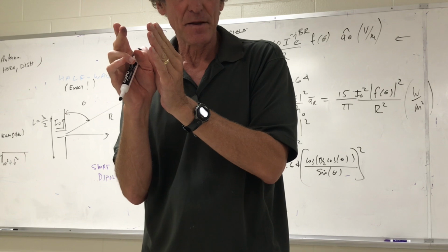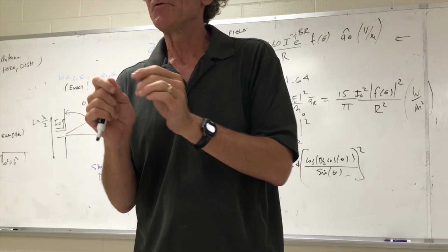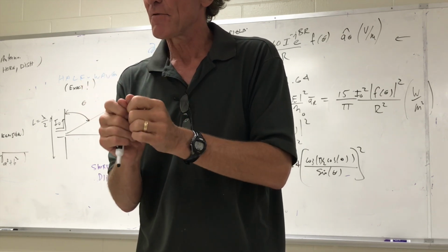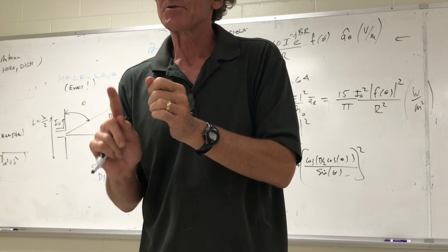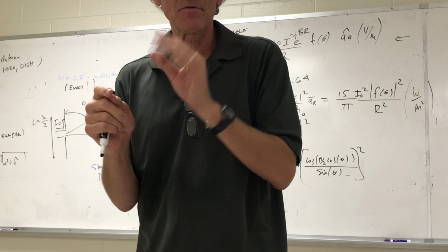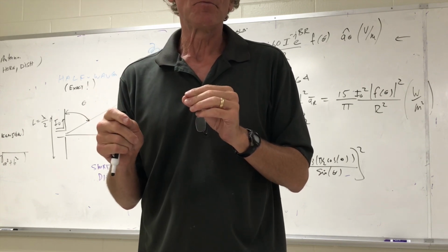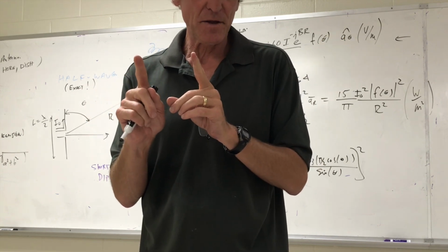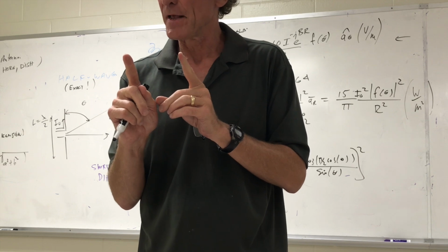You all agree? Now, if you get that and you drive that at exactly a half wave, and you measure the current going into that antenna, you get an impedance of 73.2 roughly, plus j42.5 for the actual impedance that you would measure for the current driving.